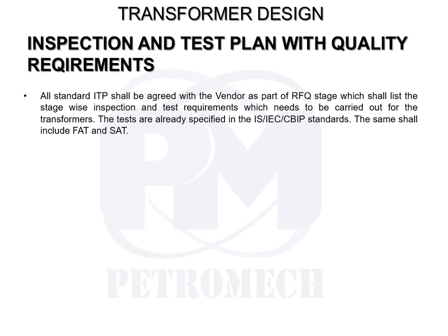It will again come back and then it will finally be delivered to site. So the factory acceptance test and the site acceptance tests have to be included in the inspection and test plan, and accordingly the factory acceptance test and site acceptance tests will be duly performed on the transformer.